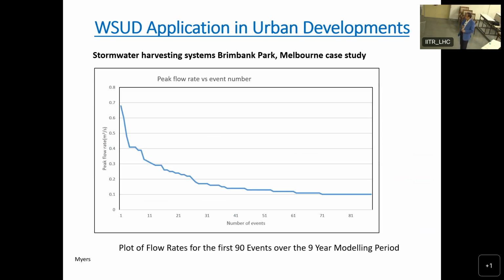And then we got this type of curve and we realized, okay, roughly around 1.5, 1.6, we are losing only limited events by taking the peak flow of 0.68 for designing our infrastructure. Rather, we miss out these few peaks and design for the remaining runoff which is coming.